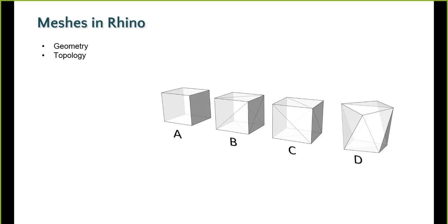Now you can also have one of these, if you took away, say, the tops of all of these, you can have other types of edges. So an edge that has 2 faces is considered clothed. It's sort of covered on both sides. If you took off this top and just had this single face, you'd have what you call a naked edge. It only has 1 face that it's adjacent to.